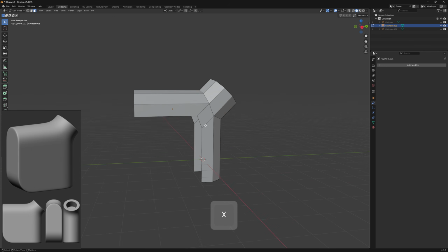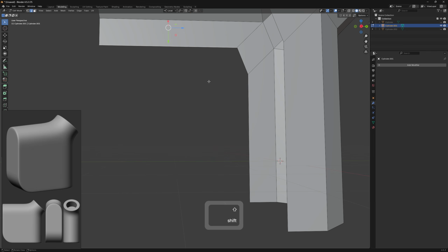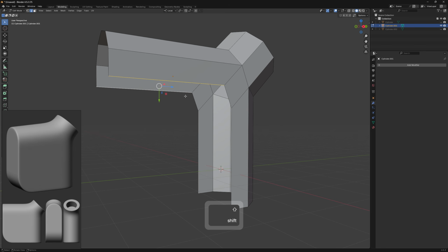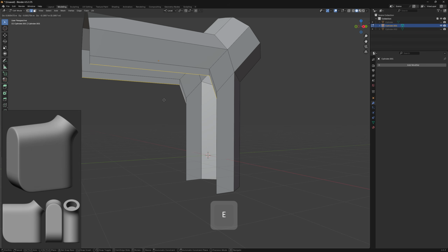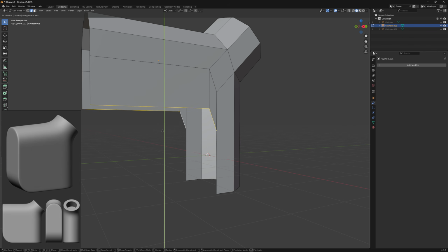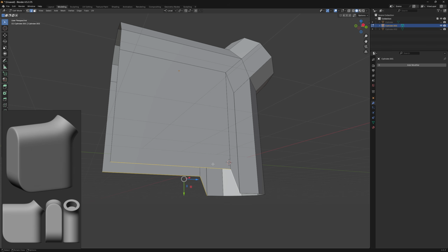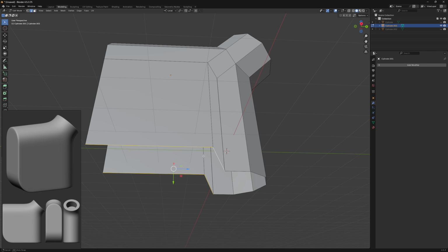click on Faces. After that point, it is going to be quite easy. We just need to select those edges, tap E, which is the extrude tool. I will lock the axis. Once I have done that, I want to scale those edges to 0 to flatten them out.